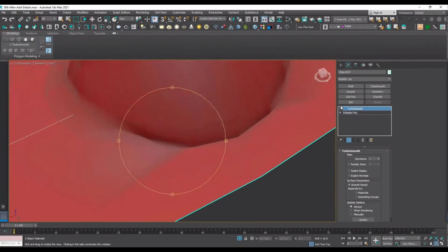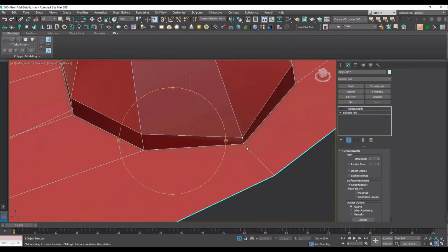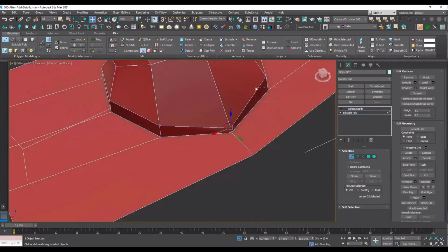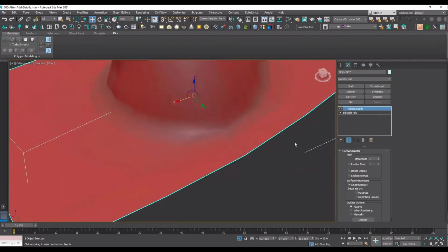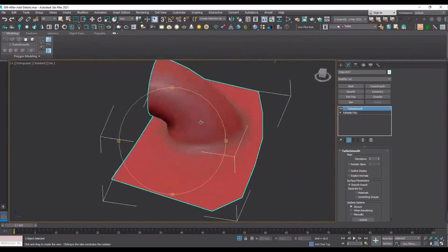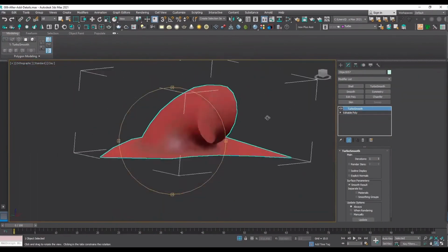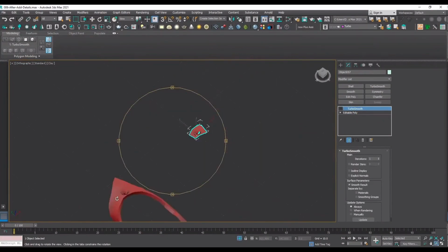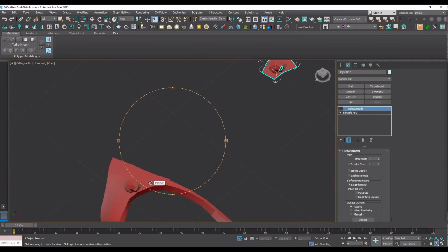And now you can see we still have some vertices that haven't been welded together. Using the weld command, I can fix these shading issues, and just like that, our first step is kind of done. We have successfully attached our detail on top of the surface.